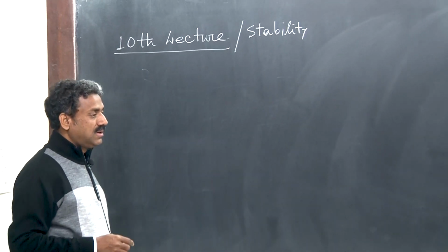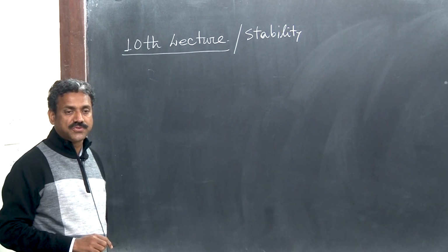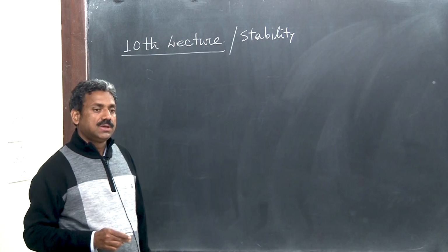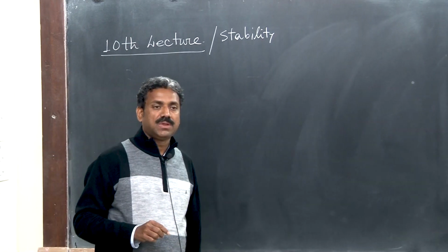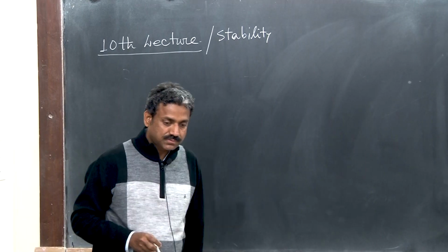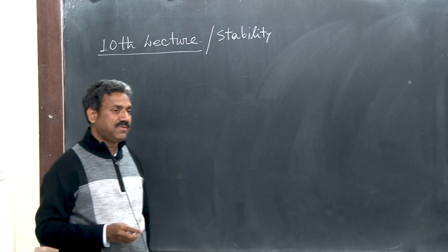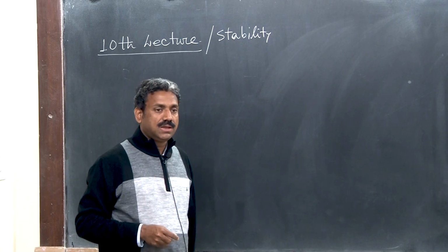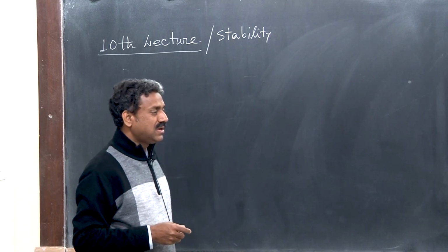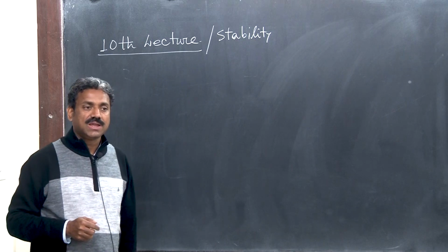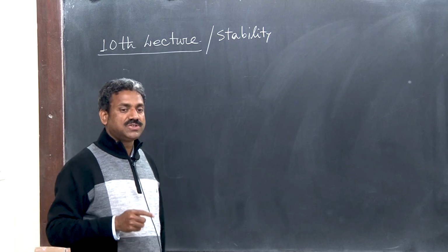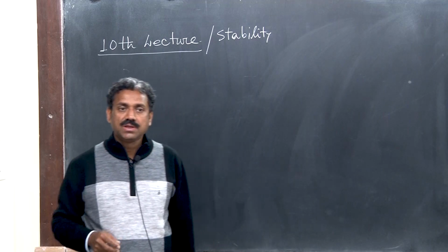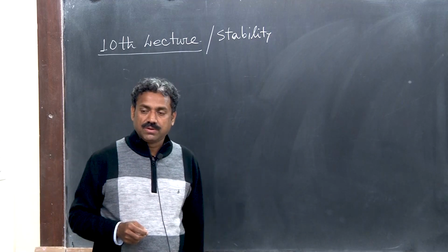So, we have derived the equation for the strain energy. If you can recall, the strain energy contribution was from the two translations U and V as well as the twist. The twisting degree of freedom, that is the twisting angle beta, was considered while deriving both components of torsion. One is St. Venant torsion and another is the warping torsion.